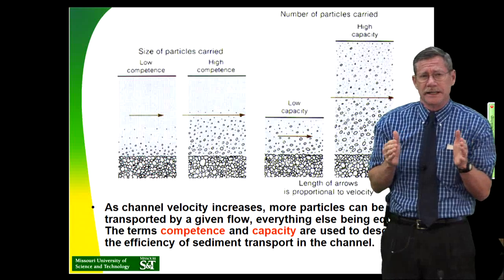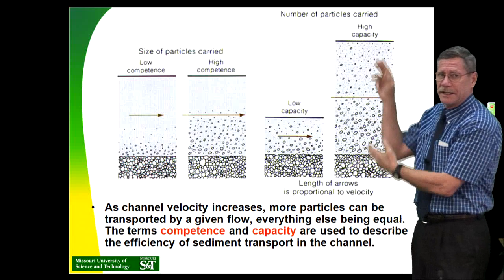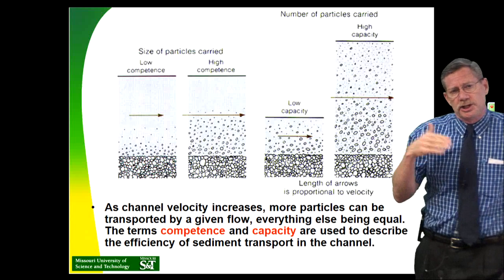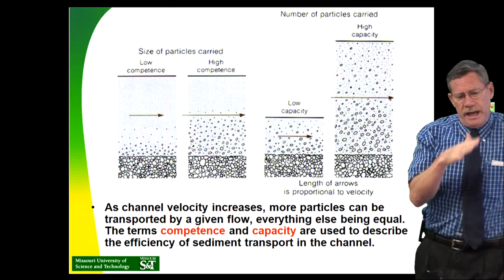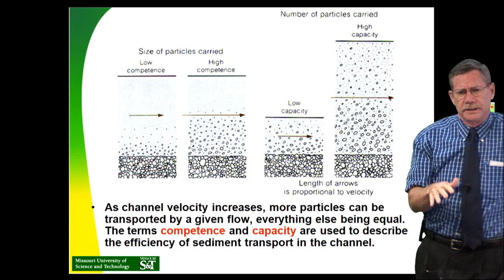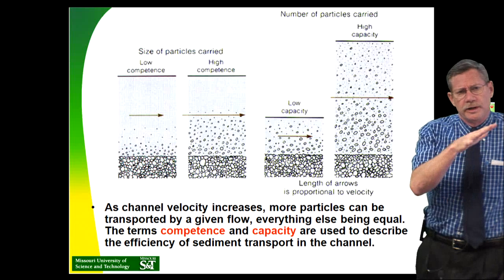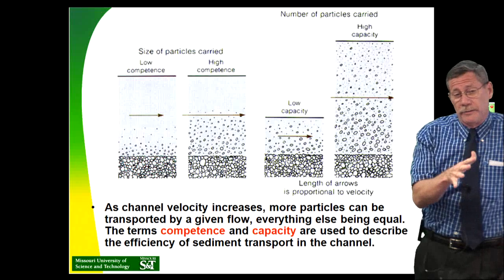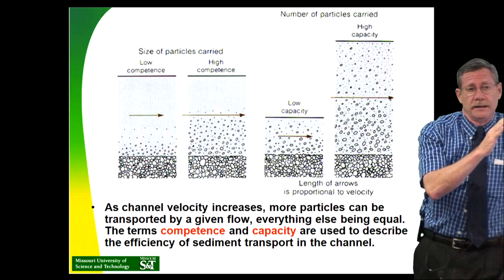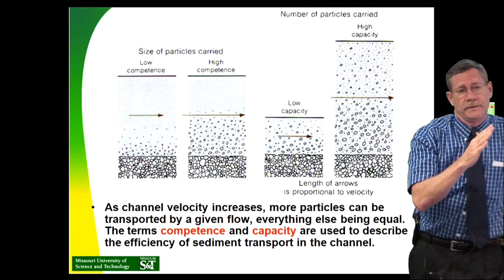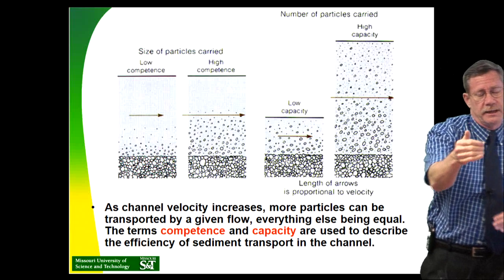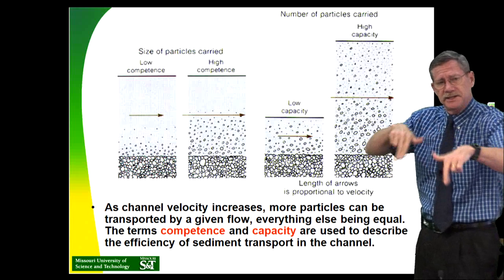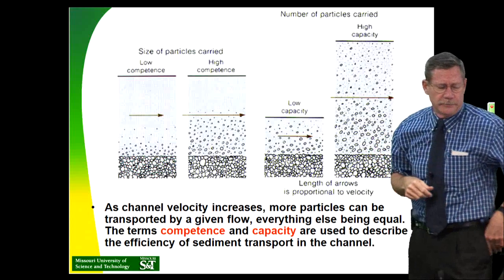So in hydraulics, what kills you in this kind of stuff, especially with bank repairs and with bridges, is the change in Manning's coefficient, the roughness coefficient, that you engender when you put an improvement in. Ideally, when you do a bank repair, you'd like to put something in there that has the same coefficient as what's upstream and downstream, and you're going to have fewer problems on the transitions with back eddy erosion.